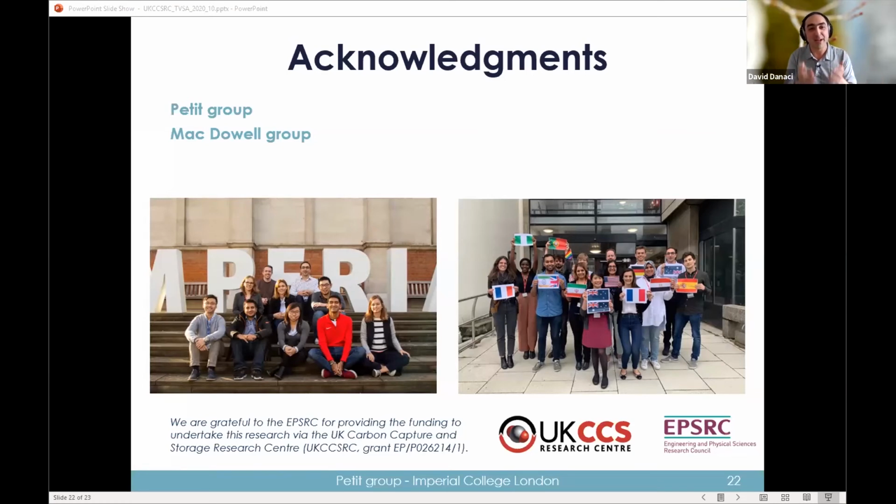So that's really the balance with every adsorbent, not just MOFs. Even if you look at zeolites, which are water tolerant, high silica zeolites, very poor CO2 adsorption capacity. So MOFs for steam regeneration may not be a good idea, but that's where indirect heat transfer might help you. It doesn't need to contact the water.